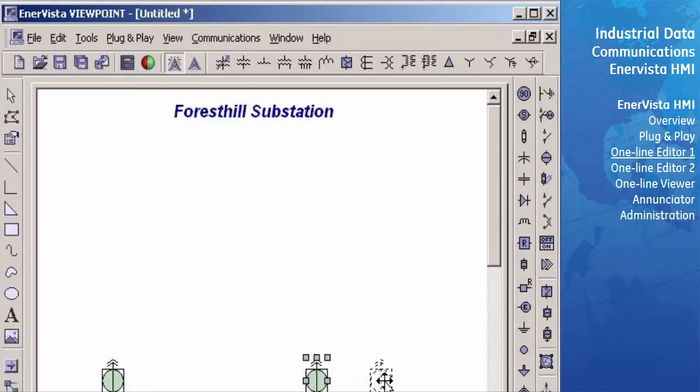You may now move this new copy of a device to another part of the schema. You can also copy and move devices by holding the Control key and then dragging the copy of the device to another place. If you also press the Shift key while dragging, the copied device can be moved on the same horizontal or vertical axis. Some of the components may need to be rotated or scaled accordingly to accommodate our diagram.